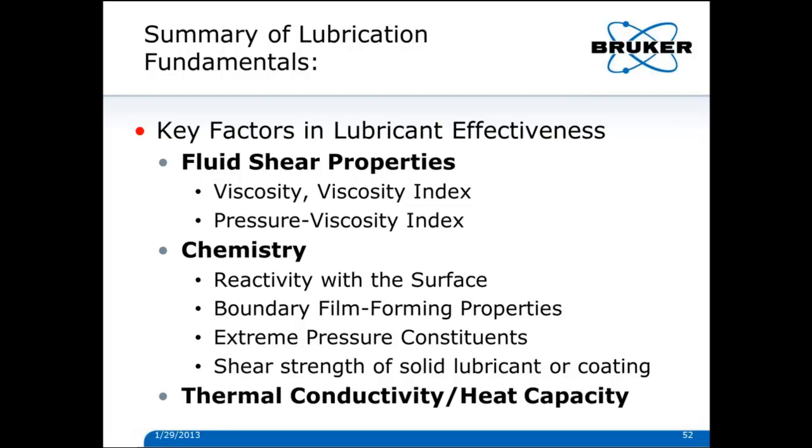a boundary. The extreme pressure constituents, so that when we do have contact, we don't get metal-to-metal welds or plastic-to-plastic welds or plastic-to-metal welds, which is an adhesive wear mode. We'll cover that in the next section. And finally, the shear strength of solid lubricant coating, that's a key factor in this lubricant's effectiveness.